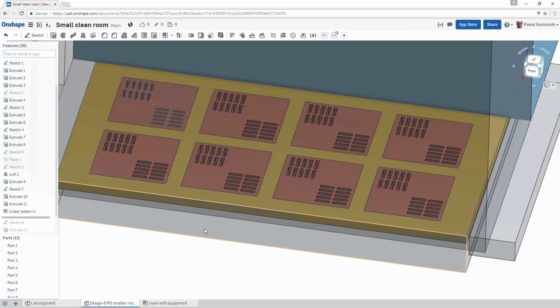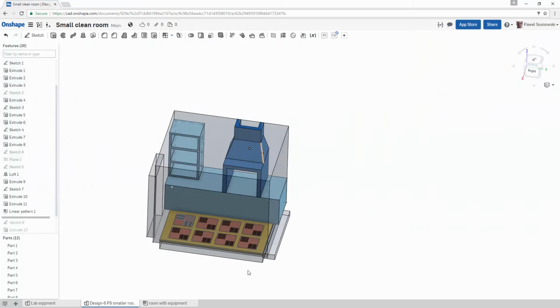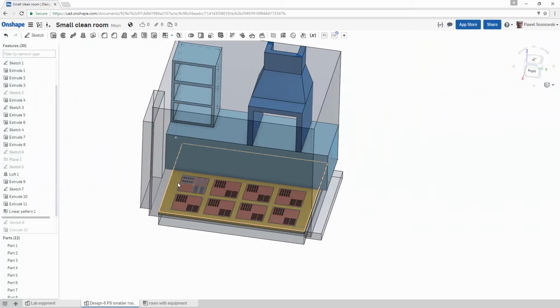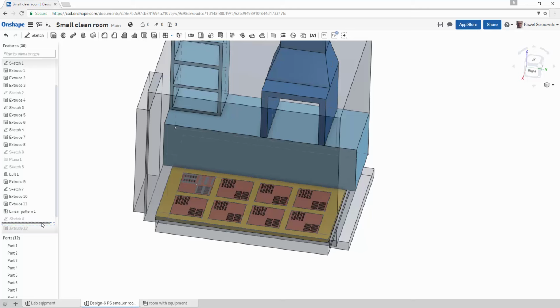But in order for the mesh to capture their presence, it is required to give them a little more significant thickness. So we're doing just that. At the same time, even though we're performing this kind of action, it will not have a big impact on the overall performance of the whole domain, since it's much bigger than this element.